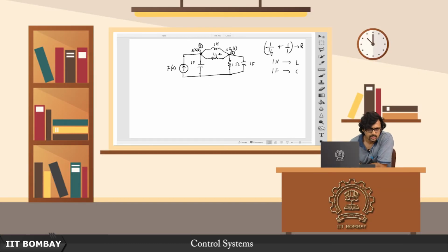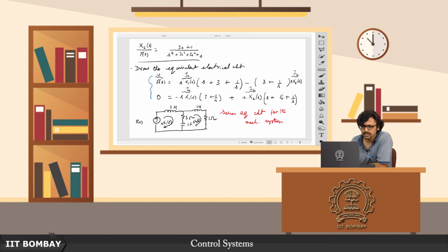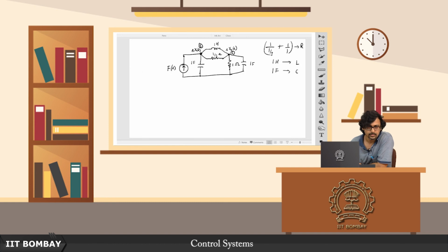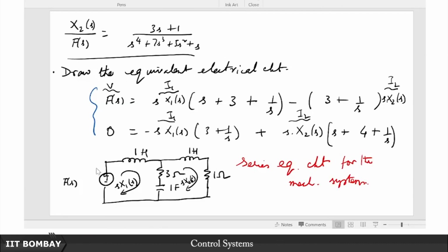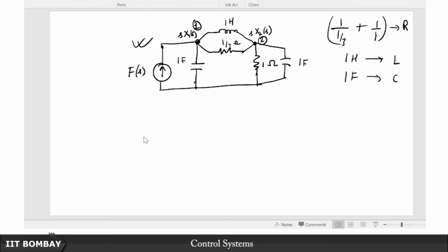Doesn't that match up to this coefficient here? You see, this is the total resistance, this corresponds to the total inductance, this corresponds to the total capacitance, out of which this much resistance is common and shared with node 1, and this much inductance is also common and shared with node 1. So that is what we have shown here. This is exactly the same circuit; this parallel equivalent is depicting the same differential equation as the circuit which was depicting the series equivalent. So we have basically seen that there are these analogies between the parallel equivalent and the series equivalent of a circuit.